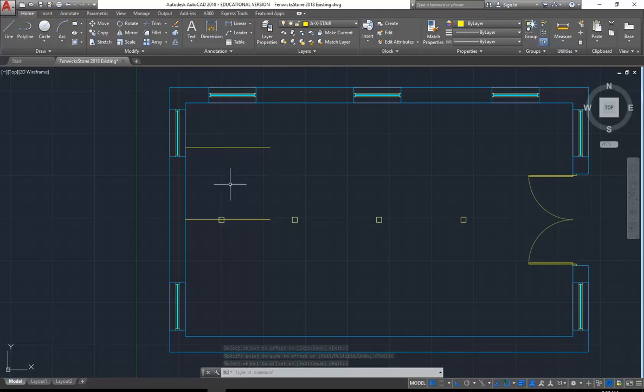And then I'll draw another line from the post, so just using the line tool again, and then I'm going to come up and just draw perpendicular to the new line I've just created. Oh, 1,000. So from the wall to the post should be 1,000.